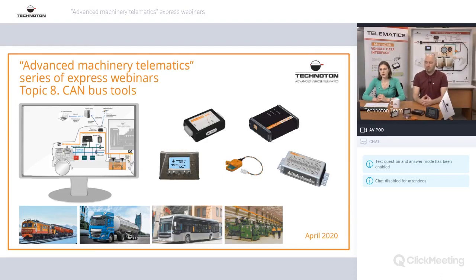When we're talking about a place where to get all those parameters, sometimes you wish to connect to the OBD port, but generally the OBD port is for diagnostics purposes. We always recommend to find another place for connection that's responsible for the engine control unit or ABS unit, the control unit of the CAN bus of the vehicle.